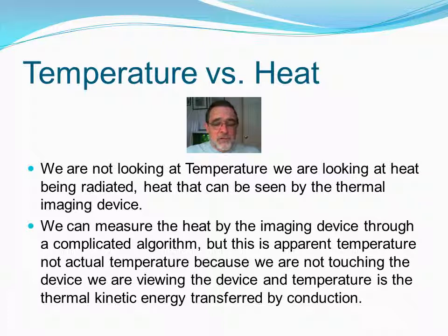But you need to understand the conductivity. You need to understand the emissivity. If you have your emissivity off, you could be considerably off in the temperature that you indicate, and that is of course the rating of the problem. The seriousness of the problem is determined by that. So it is the apparent temperature, not the actual temperature, that you're looking at.